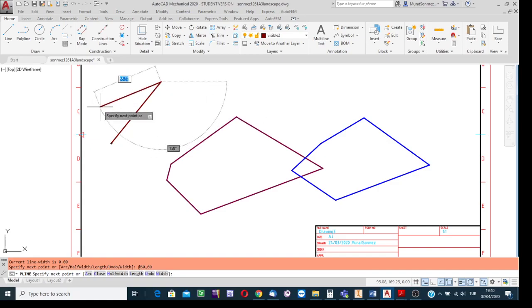Okay, say that now the second line is to be created extending to the left and in the down direction. Okay, the simulation is still the same. AutoCAD is just ready to gather the numbers as length and inclination angle. But at this stage, I'm going to teach the software that it is not the case. Into the highlighted box, write the number, say that it is 60, but it is not the length. If it were the length, I would click on the tab key.